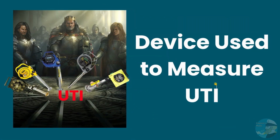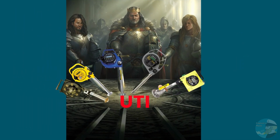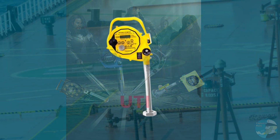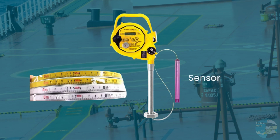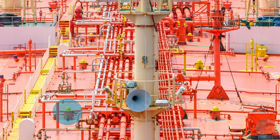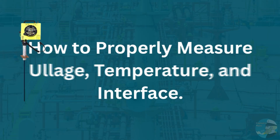To measure Ullage, temperature, and interface, a portable device called a UTI meter or gauge is used. This equipment has a probe with sensors attached to a graduated tape, which is lowered into the tank. The UTI meter emits beeping sounds when detecting oil or water, while the temperature is displayed digitally. Yes, there are tank radars installed, but they may fail or create huge discrepancies, so double-checking with the UTI meter is a must. How to properly measure Ullage, temperature, and interface.